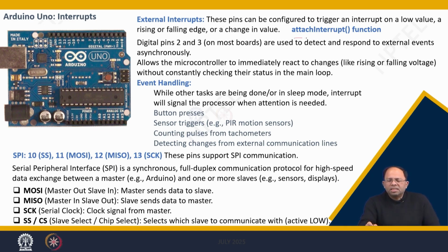So that function is the attachInterrupt function. Now what it does is, suppose I have an accelerometer connected, right? Nothing is happening. Now somebody moves the device. That accelerometer will detect that some change happened in the signal, and as that accelerometer is connected to the interrupt pin, the pin understands some change happened, and when that change has happened, it will do some actions, right?